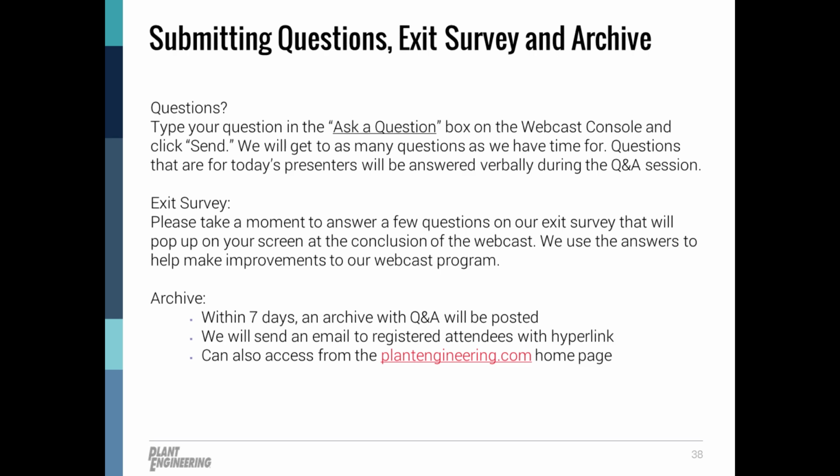Thanks, Ronnie. Michael, what type of damage can VFDs cause on motors? Yeah, very good question. A lot of people talk about the benefits of adding a variable frequency drive onto a motor, and you will find less talk about some issues with adding VFDs onto motors. Because the VFD output is not a perfect sine wave, you're passing a kind of square wave, a pulse width modulated signal to the motor. You're going to see some pretty severe peak voltages at the motor windings, and very quick rise times. Inverter duty motors, or inverter rated motors, though there's some question in the industry about those two definitions, will have VFD rated cables that go up to a higher voltage. Most of your low voltage motors will have up to 600 volt winding cables. You will have higher voltage ratings.